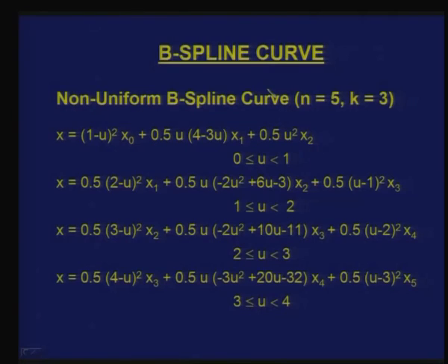Now, let us try to elaborate on the same definition which I have chosen for a non-uniform B-spline curve, where n is equal to 5 and k is equal to 3. I have written down the parametric equations for the individual segments. Earlier the definition was common.